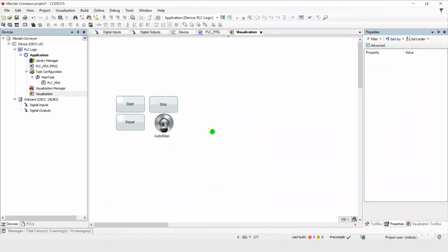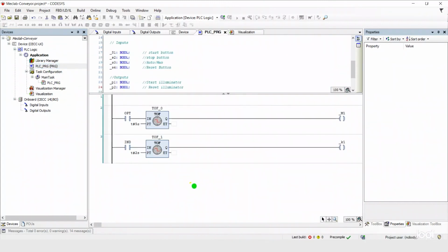Okay, now we need to include this in our code. Where do they start? Now, this is where ladder becomes a problem, because to have something happening in a sequence with ladder, it's very difficult, especially when you have a sophisticated system, which I'll show later in the next course. So now you're going to use lots of flags so that you can have a set of conditions for the different lines. So this is a headache when it comes to ladder.